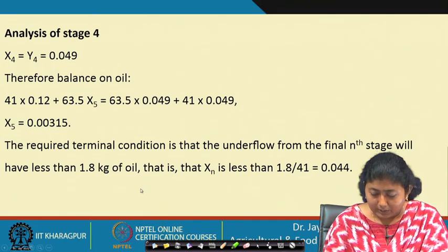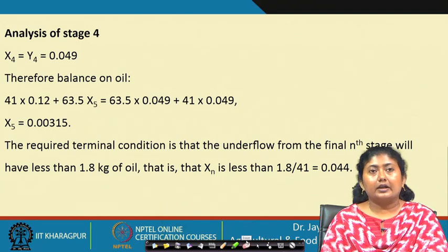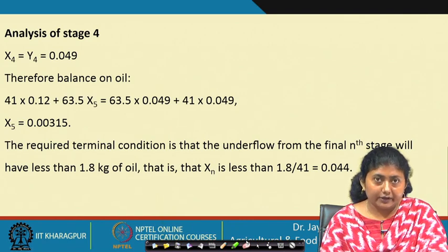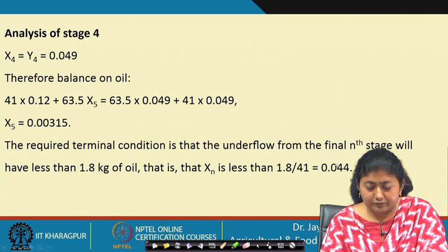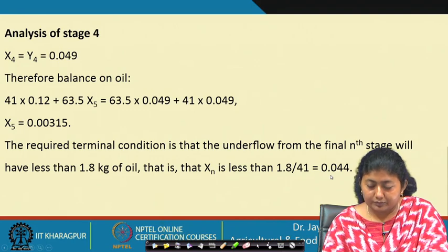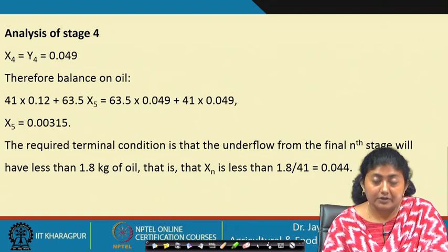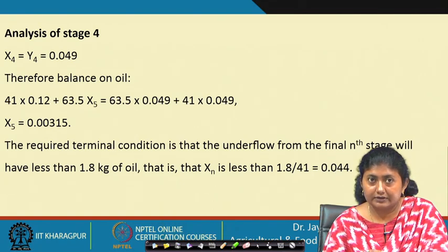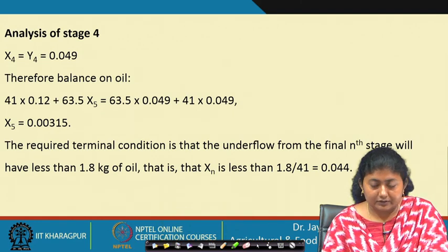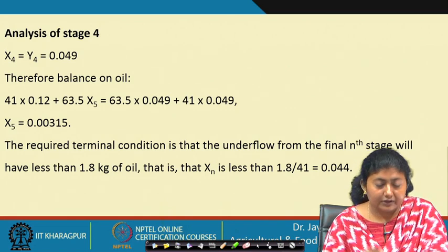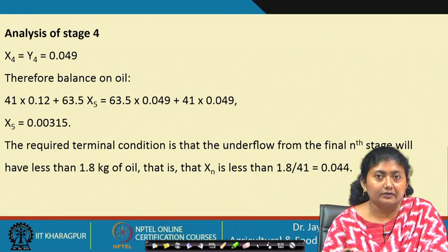Okay. So, this is how you can design when you want to set up any solvent extraction, or for example, a leaching setup. For that, you have to think about what your sample size is, what the flow rate is, how much oil content the initial sample has, and what fraction of the oil or solute you want to separate. Based on that, you can design how many stages are required.